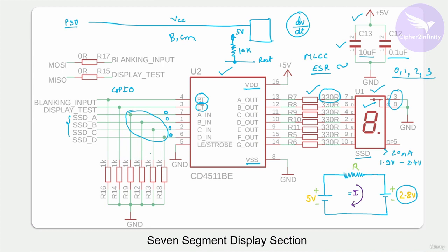Now again the question comes, why I have selected the 1K value here. It's not like you should go with this value only. You can also go for 10K, 20K, 100K, or also 1 mega ohm. It's completely fine. But the point is, if you go for a higher value of resistor, then these pins will not be strongly tied to the ground. Connecting a 1 mega ohm resistor here is actually like keeping this particular pin in a floating state only. So there won't be any effect of connecting a 1 mega ohm resistor here.